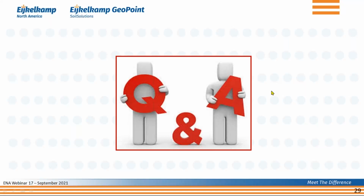Can you talk about CPT versus DMT, CPT versus shear wave velocity? There are all kinds of ways of coming up with the shear wave velocity. Whether you push the seismic sensor with a cone or with another device into the ground, you're going to get the same shear wave. What is really the interesting thing here is how you analyze the data.